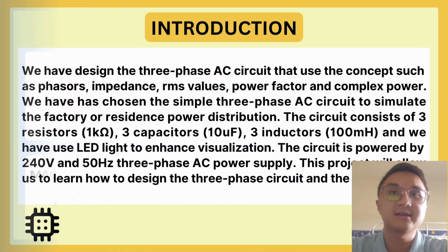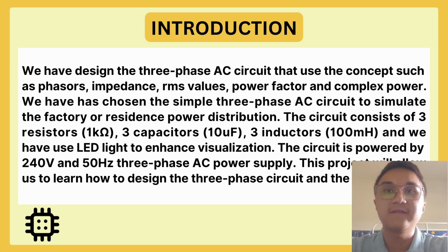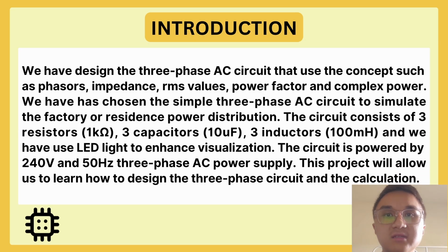Thank you. Now I will discuss the introduction. We have designed three-phase AC circuits that use concepts such as phases, impedance, RMS value, power factor, and complex power. We have chosen simple three-phase AC circuits to simulate factory or residence power distribution. The circuit consists of 3 resistors of 1k ohms, 3 capacitors of 10 microfarad, and 3 inductors of 100 millihenry.